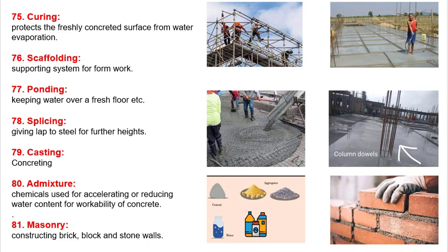What is curing? I have attached images too to make it easier for you. Curing protects the freshly concreted surface from water evaporation. When you do fresh concrete, it is important that we stop the water from the concrete from evaporating, because it can badly affect the hydration of the concrete.